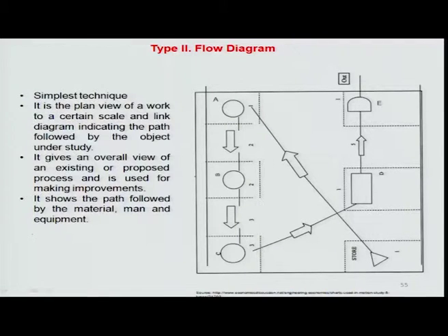The purpose of a flow diagram is that, in the simplest manner, you could record the way material is flowing from stores in terms of various things like transportation of the materials, operations, and whether some inspection is involved. In this case, for example, a material flows from a permanent storage all the way to, let us say, station A, which does operation 1, beyond which the material flows from station 1 to station 2, so there is a transportation of material between station A and station B.